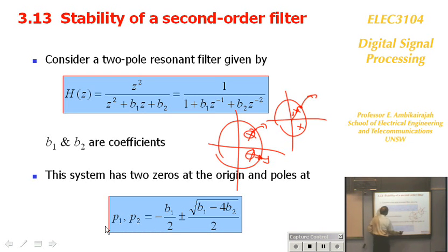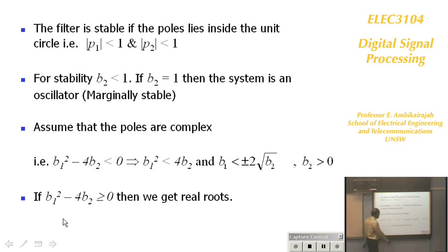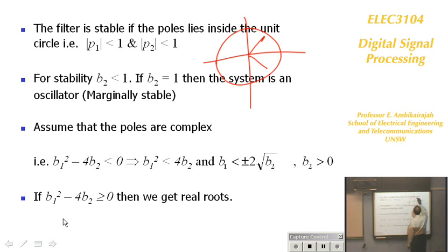So, how do we go on? Let's take this equation, which gives your second order poles, and find its roots. Roots are given by (-b ± √(b² - 4ac)) / 2a, and that's what you get. b1, b2. Now we know these are the poles. Once you know the pole position, you know its magnitude, that's the distance, which must be less than 1, and the second also less than 1.